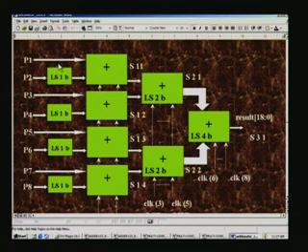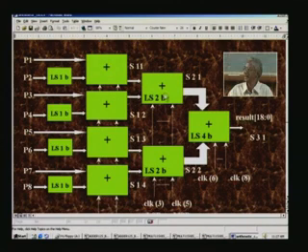What we have seen is the total number is bifurcated into two, roughly half. One half we call LSB, the other half we call MSB. So we add only the LSB here, and the carry will result, which will add with the MSB of these two at the second clock, and then concatenate the two to make one complete S11 sum there.